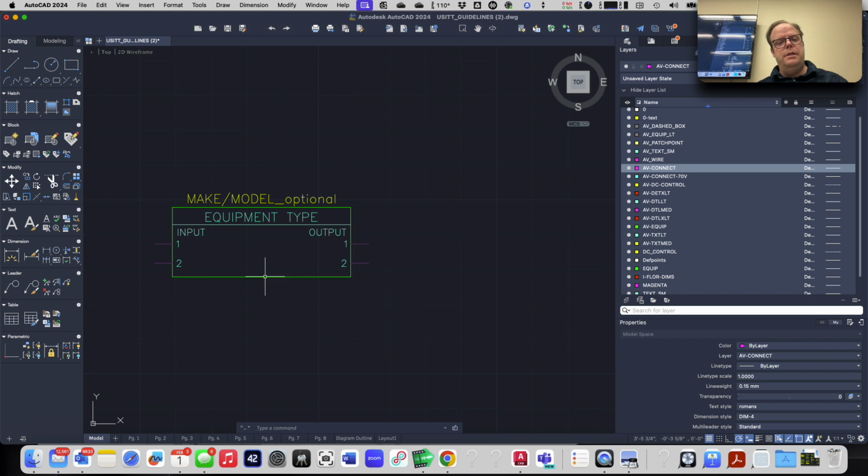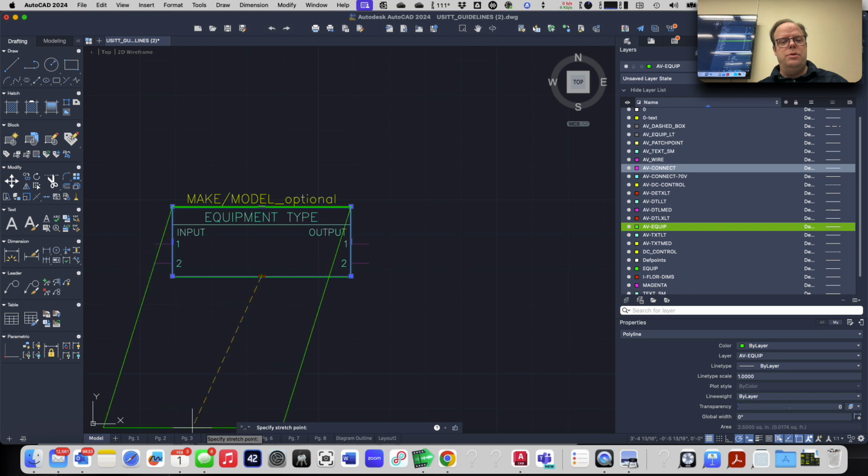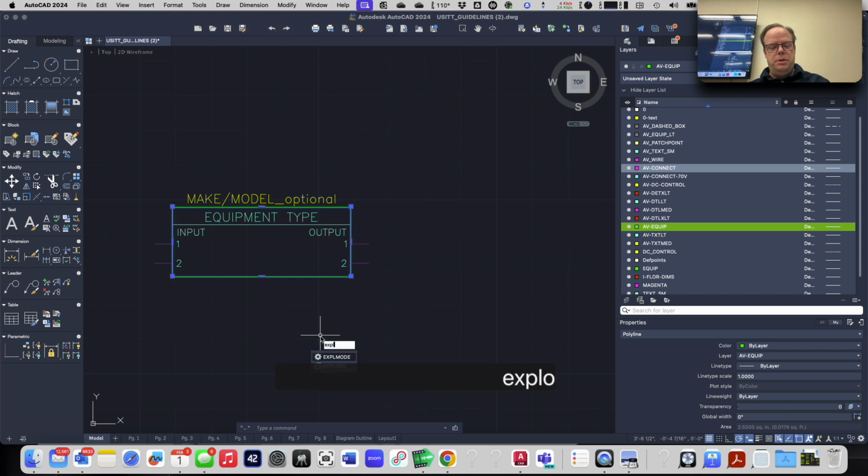And here's the way I want you to get used to doing that. If you select this rectangle here, there's this weird draggy thing that AutoCAD will now let you do, where you can actually click and drag on this thing, and you can do this sort of thing. Don't do that, okay? Because it's too easy to make your thing skiwampus, okay? What you're going to do instead, I'm going to teach you one more command that you are allowed to use, and it is called explode. We're going to blow up this rectangle, okay? So while it's selected, literally type the word explode.